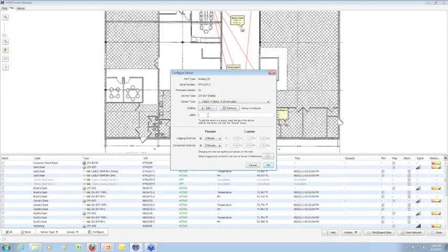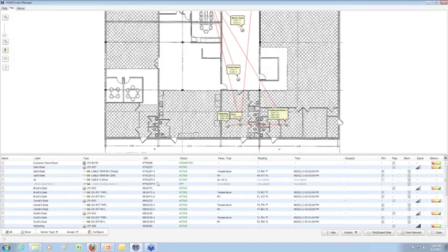Now what that's going to do is save that scaling information, so we can get out of the engineering units. And now that's being stored to the database. So you can see the type of cable that you have connected up to it, and then you have your scaling information here. And next time the first reading's taken, you'll actually get your measurements in CFM.